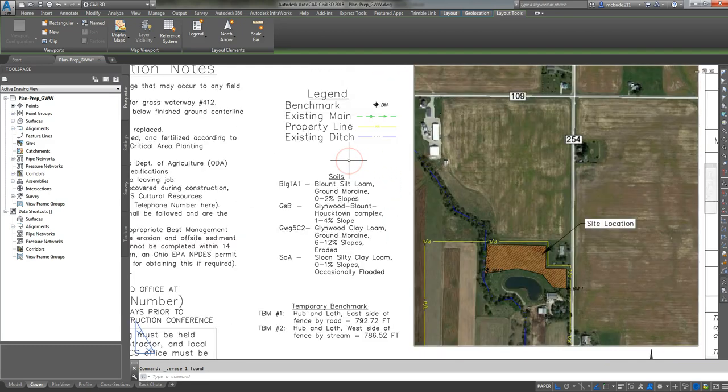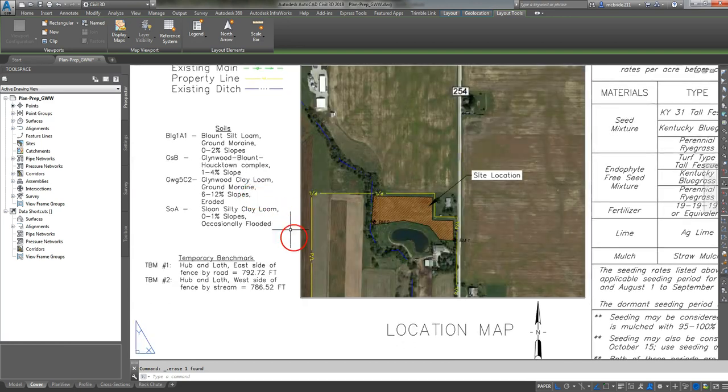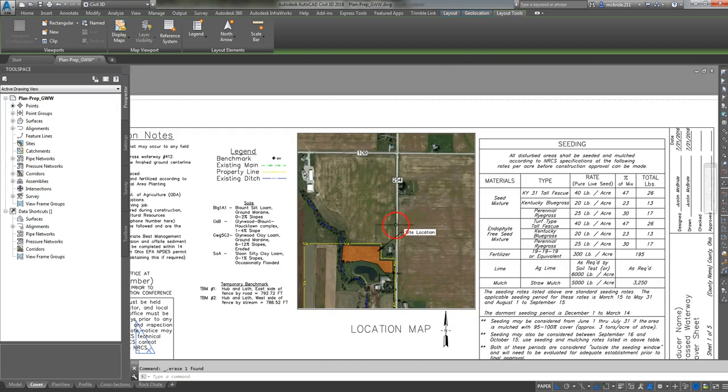Okay, so it's important we have the map along with a legend and a north arrow. And you can argue with me whether or not we need a scale. I think the more important thing to know whether this map is to scale is to know where the intersection point of the two roads are. If we know that, we can at least get the general location of where the project is located. That's the whole point of this map, is just to show the location, not necessarily to get standard measurements of detail off of it.